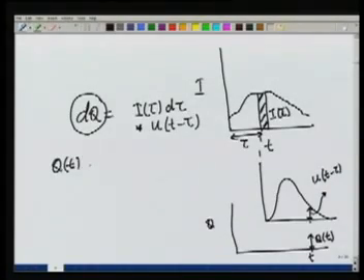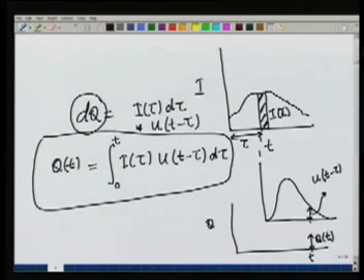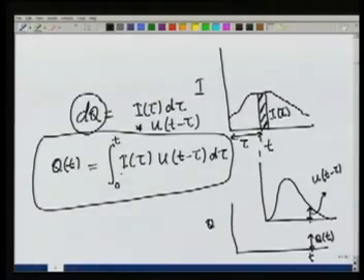we have to integrate it from 0 to t. So this equation gives us a way of finding the direct runoff ordinate at any time t. Now if you look at this expression, I(tau) will of course be 0 beyond t0. So the duration of rainfall is t0. So if t is more than t0, then we have to perform this integral only from 0 to t0.